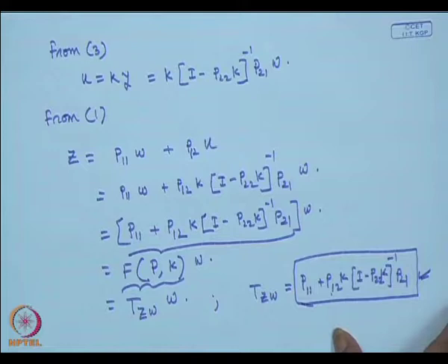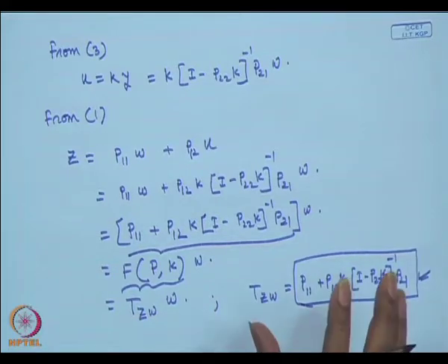First thing we know is how to represent in general a dynamic system: there are basic 2 inputs, 2 outputs. One input is the exogenous input, which consists of noises, disturbances, command input, and the other input is the control signal input, which will regulate the system response. The output Z is called the regulated output.